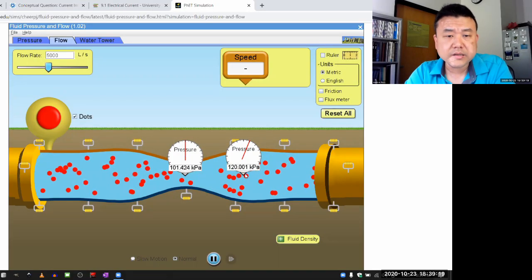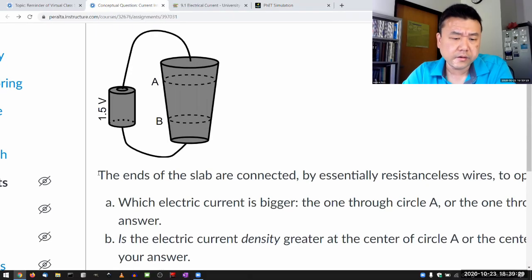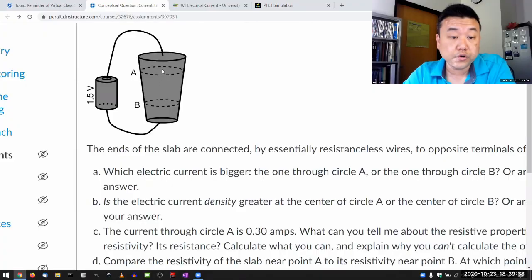And you can see a similar situation with the electrical current flow here and voltage here. So I said, referring to why the correct answer here might be unintuitive, that when you are looking at resistance per length, that resistance per length would be less here compared to here, but still the amount of electric current flow is the same. Well, if you look at the voltage change per length, what you will find is that the voltage change here is less per length compared to the voltage change here per length.